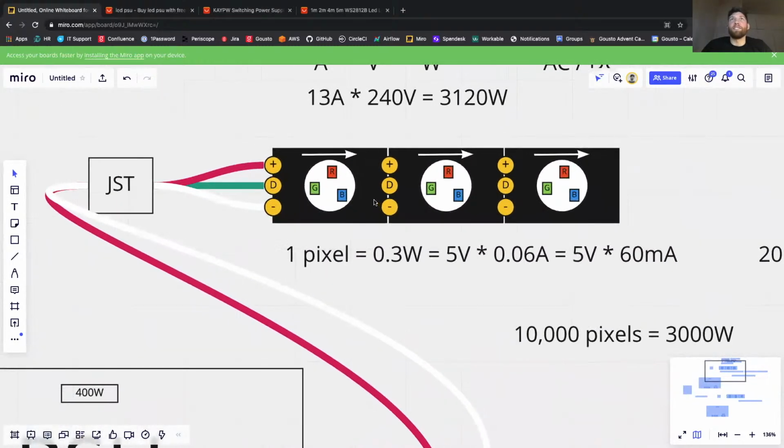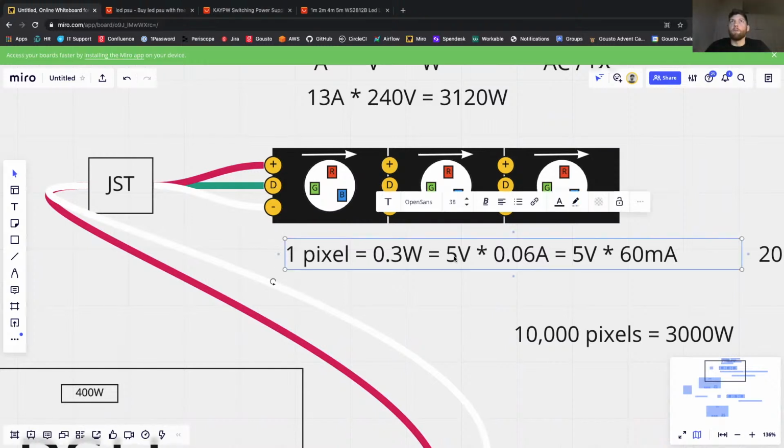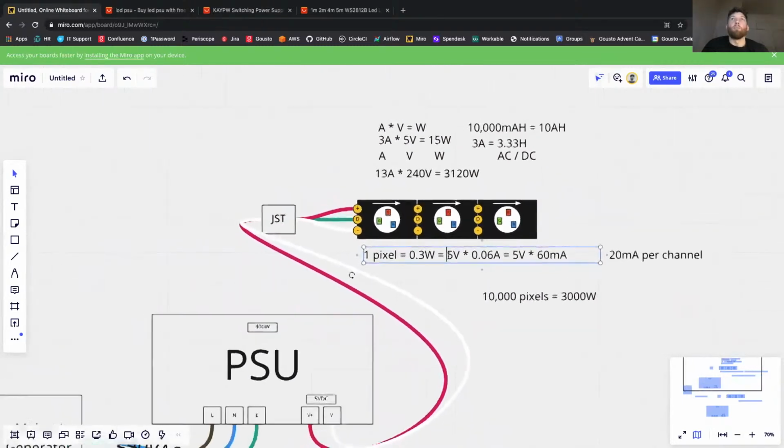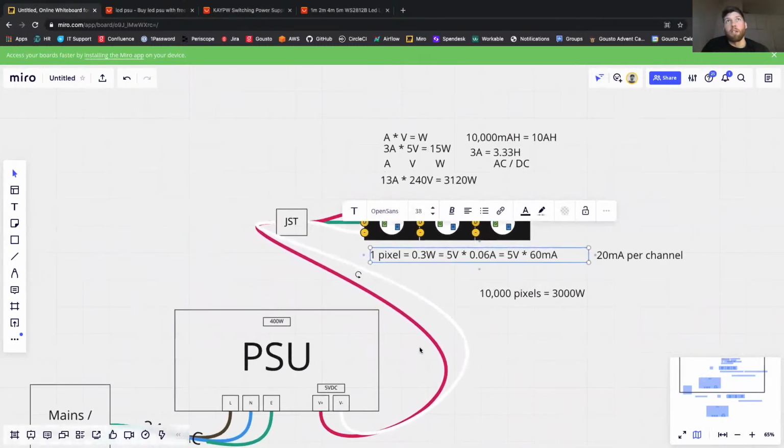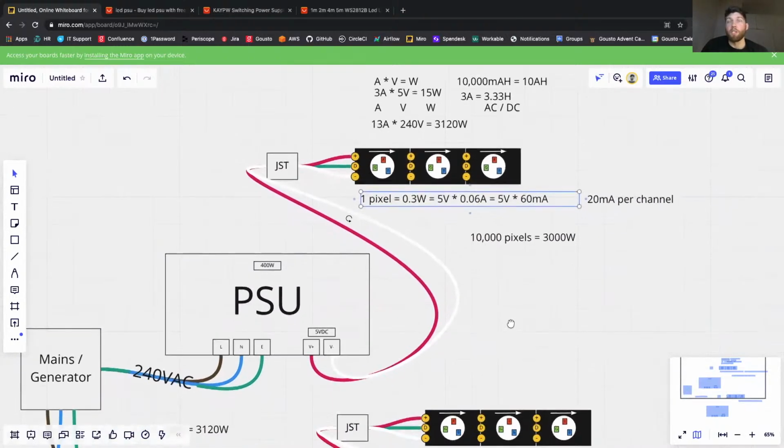And in reality, since they're well-engineered, sophisticated electronic systems, they can tolerate a little bit of variance around that 5 volts. So it doesn't have to be, in practical reality, bang on 5 volts. I think they can operate down to something like 4.5 or maybe even 3.3. Don't quote me on that. But ultimately, it is possible that you make your cable so long that it incurs a quantity of voltage drop, which is unsustainable